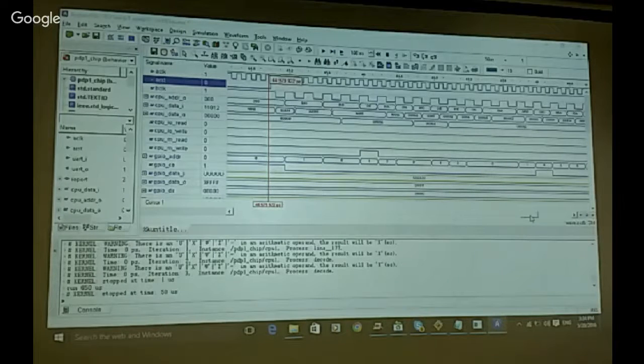Okay, I think now I remember when I did the 8080 implementation, what I did was not doing it this way, but to debug the CPU alone. Use the CPU as the top module, and then exercise the CPU by itself. In exercising the CPU by itself, what I was able to impose on the CPU is the memory input bus. Because if you only exercise the CPU, you don't have memory.